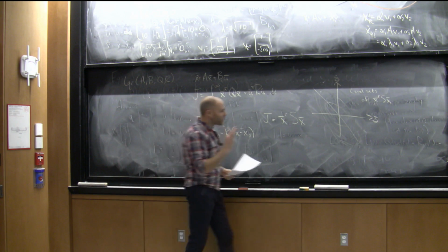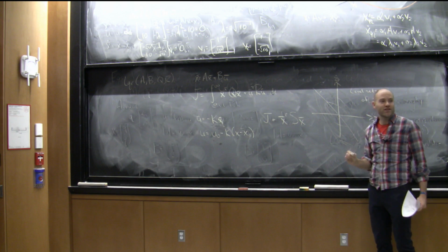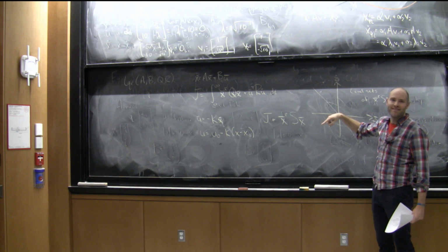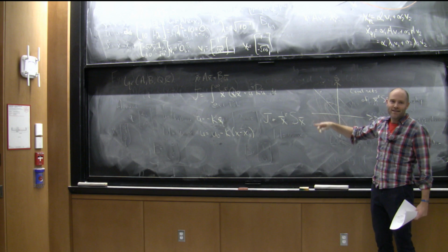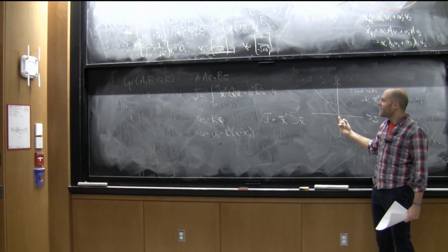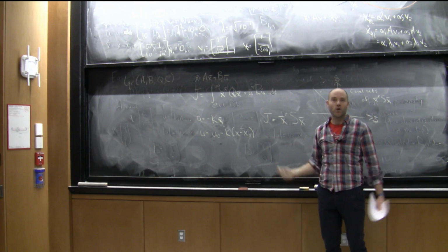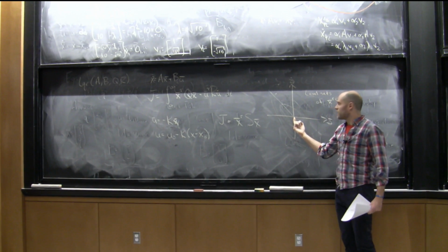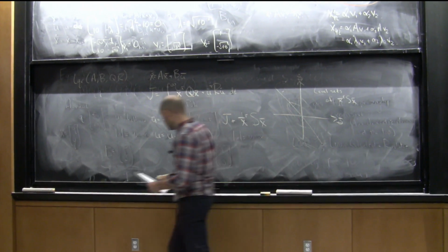So there is a requirement, which is that you have to be controllable, right? You have to have enough actuators. Like if you're too cheap and you didn't put any actuators on your robot, you're not going to be able to run LQR and get a controller out. And so in MATLAB, it'll say A and B are not controllable, right? And so what does controllable mean for nonlinear systems, just to be precise about it?